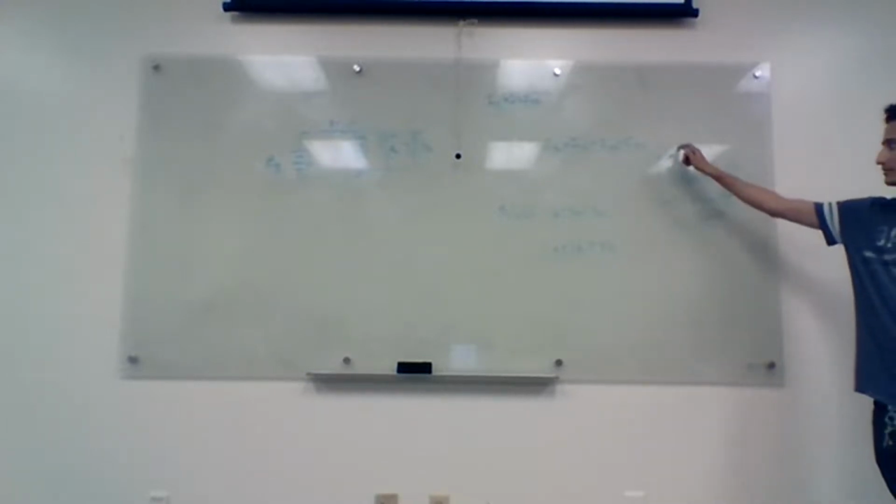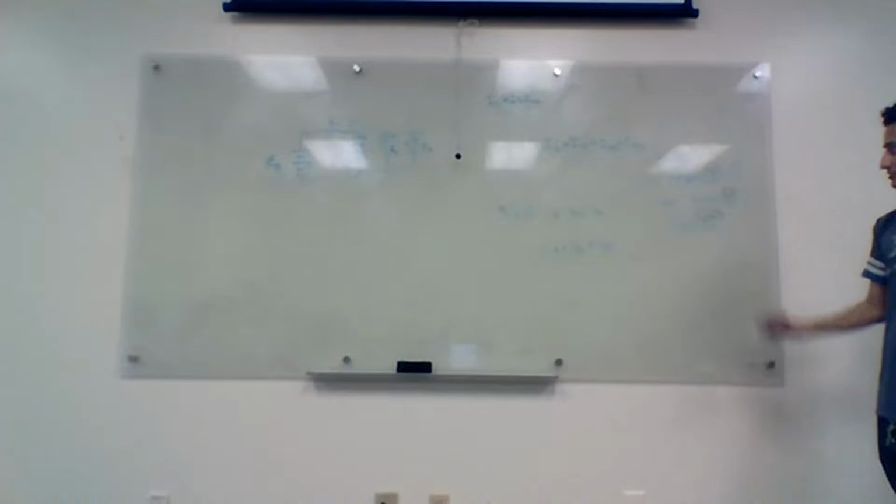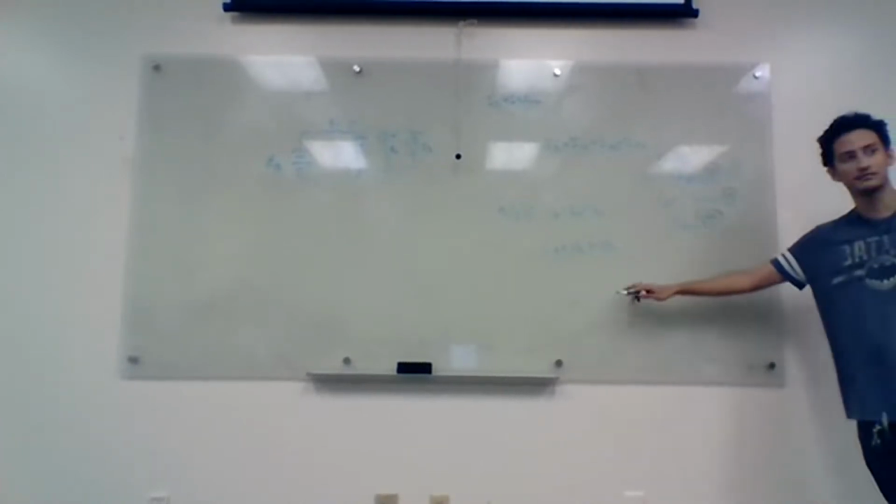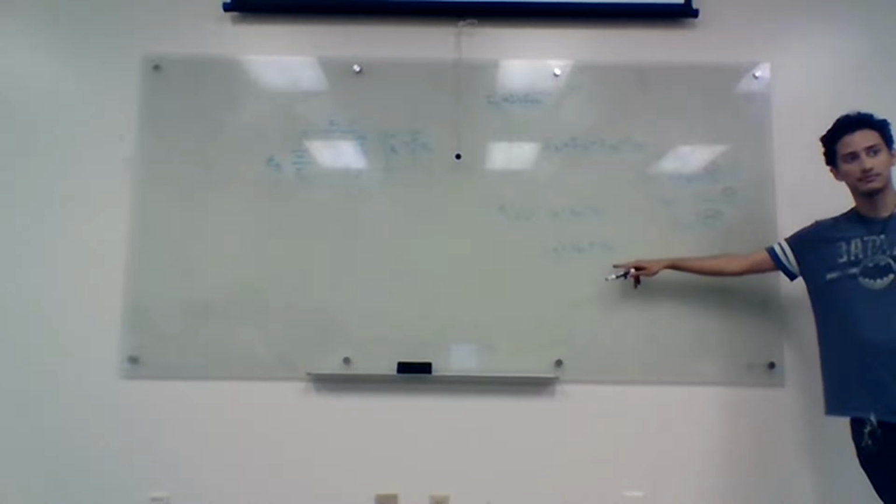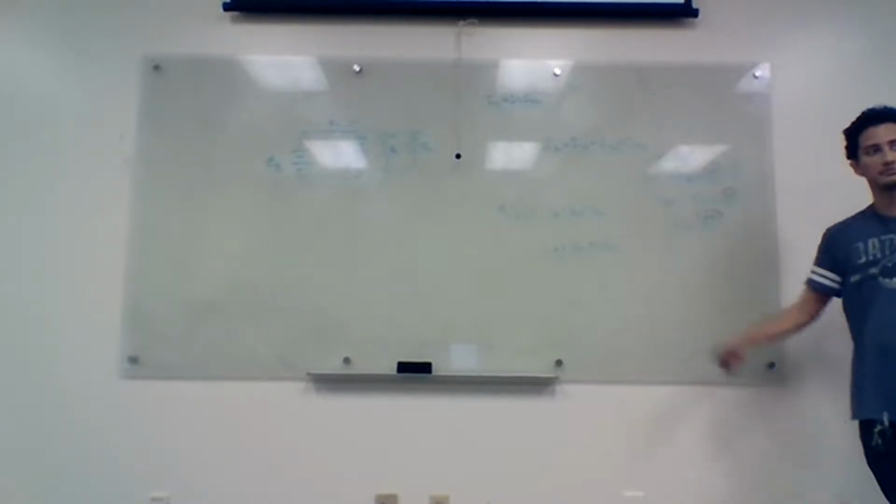Those three voltages are the same. And you can get this voltage in terms of that one from your KVL. Then you should be able to solve it. Plug it back into your KCL, solve for V_D, and you can solve for the currents.